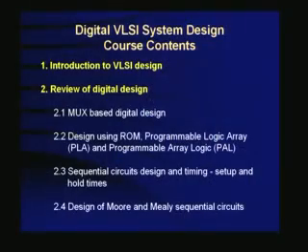But we will do system design in this course, multiple input, multiple output systems. We can do it using multiplexers, using programmable control elements such as ROM, PLAs, PALs. We will do sequential design and we will talk about setup time, hold time. These are important when you talk of design of VLSI. And we will do sequential circuits with applications for pattern generation, for example, pattern detection, for example, Moore-Mealy circuits.